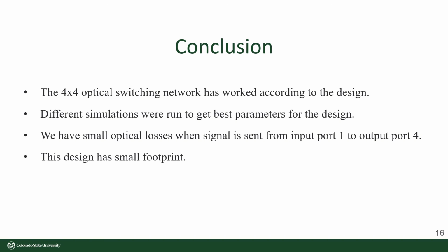So to conclude this project, we can say that after running different simulations and obtaining the best parameters, the design has worked pretty well for 3 out of 4 outputs. And we can see some small amount of optical losses at the output port 4. But our design has a very small footprint. So these are the trade-offs when we have a small footprint and do not use multiple ring resonators.